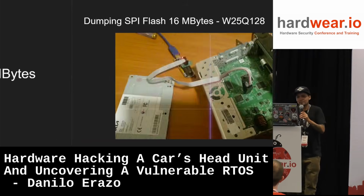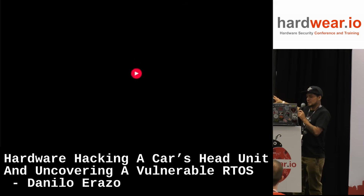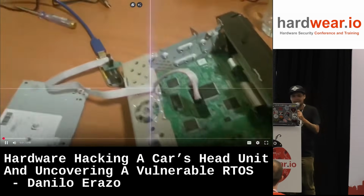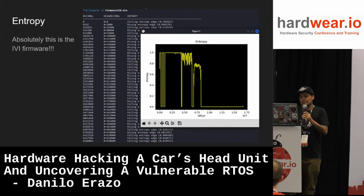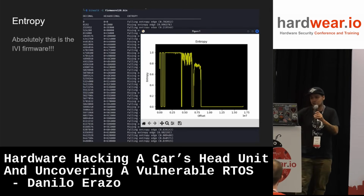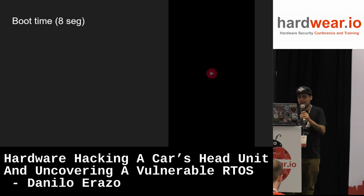Okay. So let's dump the big flash, the WB25Q128 with 16 megabytes. As you can see, right now I am dumping the second flash. And yes, absolutely, this is the firmware. Why? Because this is the biggest binary, and there are many files, compressed files and non-compressed files.